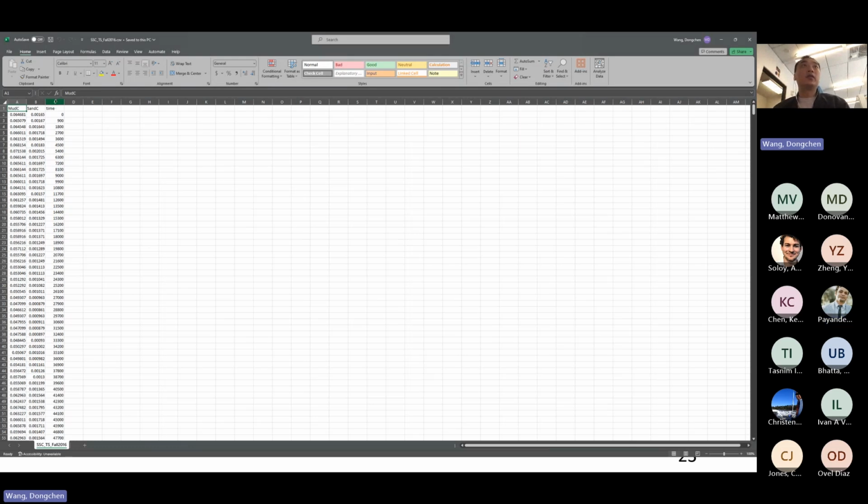In this boundary condition file you have several columns. One is time. The order doesn't matter, but you need to say this column is time. It counts in seconds, starting from 0 seconds all the way to the length of the simulation. Then you need to specify the sand concentration and the mud concentration.